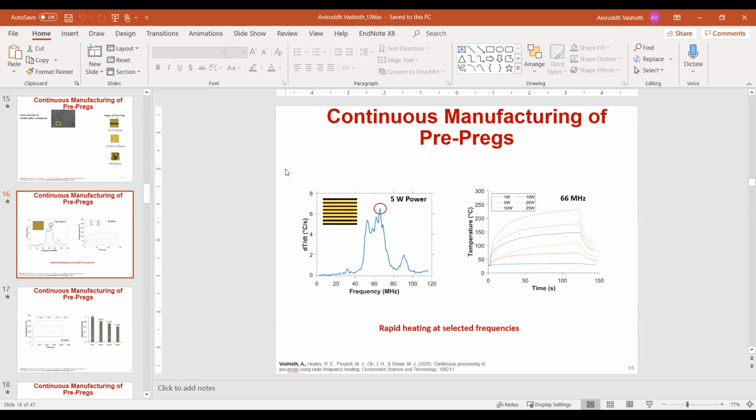So for our PEEK and PEKK material system, we typically have to get up to like 700 degrees Fahrenheit for it to really crystallize to form a semi-crystalline structure. So, a little more robust composites. Do you still think that's the case? Is that temperature range achievable?